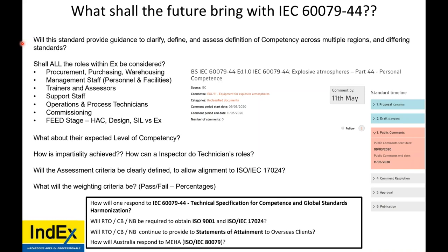If a specification or standard is wholly applied in a copy and paste method, something applied to the UK will not be sufficient within Australia or within UAE. You could be looking at black body UV temperature of 75 degrees Celsius. If a diesel tank gets up to that level, you're getting to the point where it is a hazardous atmosphere above that diesel. Vapors do start to become an issue.